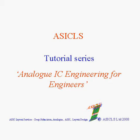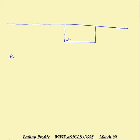In this tutorial I want to demonstrate the LATCHUP mechanism and how it forms in CMOS. First of all, we show the silicon substrate profile of an inverter, and in it we'll define our N-well implant, which we mark N-. We also mark the substrate P-. The minus in both cases means low dope.